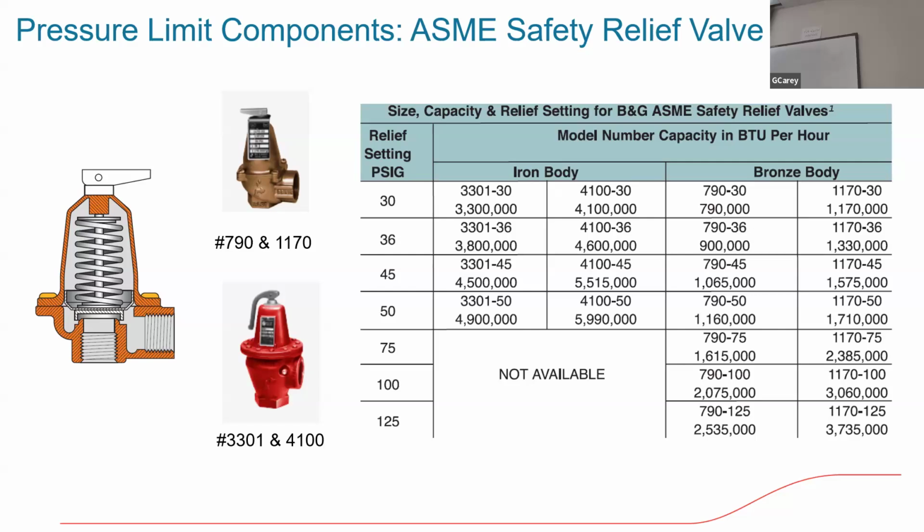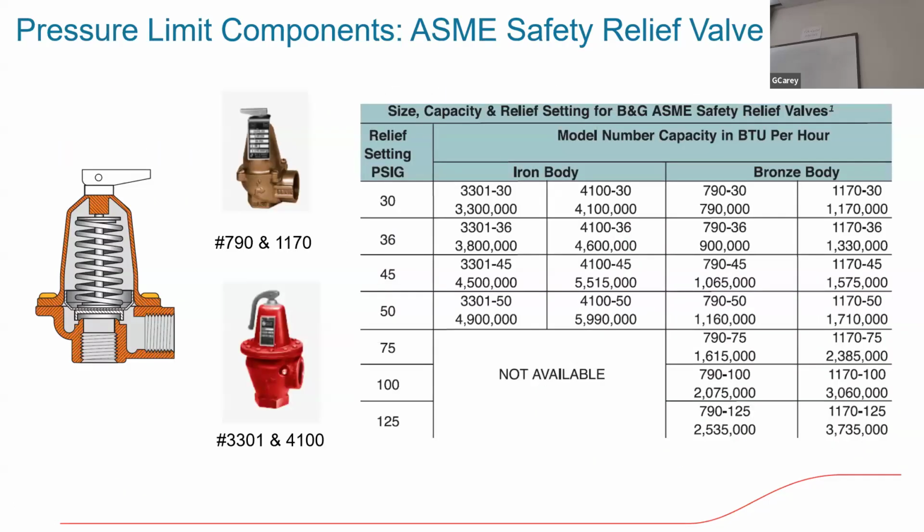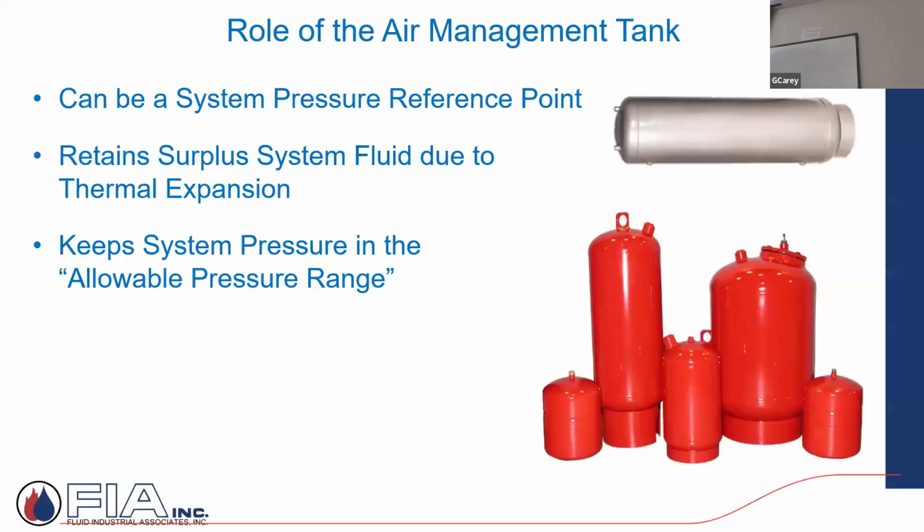So we don't want that by bad design, and that's what the expansion tank is, again, one of those pieces of equipment that if it's done right, you almost don't know it's there. When you install it correctly and you've sized it correctly, it's almost like you don't know it's there. But as soon as someone messes up or doesn't follow your instructions, all of a sudden these things become active. And then you don't have a closed system. You have an open system because it keeps opening to relieve pressure.